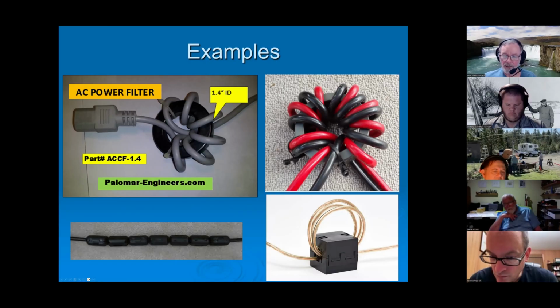It helps to keep these things as tight as you possibly can. Get the wire as close as possible to that core and keep it there. And using tie wraps to hold things in place as you wrap it. And when you need to hold things so they're really close to the core, using tie wraps really does a nice job.